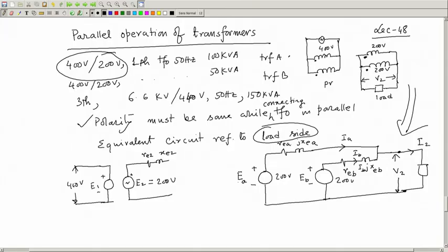Instead of doing that, purchase another transformer of lower kVA, but with the same voltage ratings, and connect them in parallel, so that the old one is not removed from the circuit. In this way, as demand increases, you can connect two or more transformers in parallel and supply the new load demand. Each one will contribute to the load.